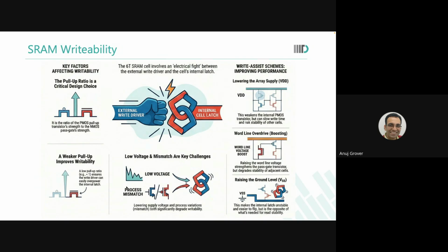Are you with me on this? So whatever you were able to observe at 0.8 earlier, with a higher VT, suppose 50 millivolts higher VT, you will start to observe it at 0.85. Are you with me? So as you increase VT, all the behaviors of lowering VDD will start to become evident.